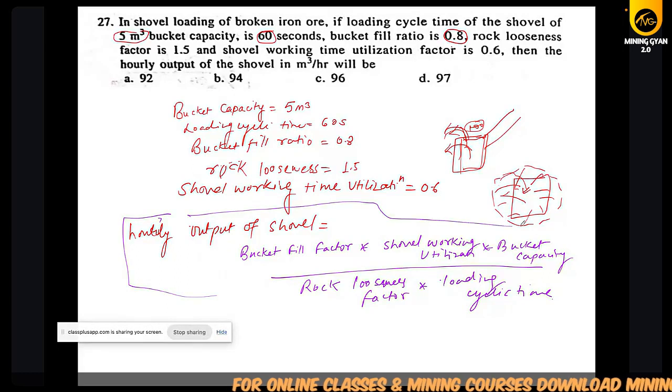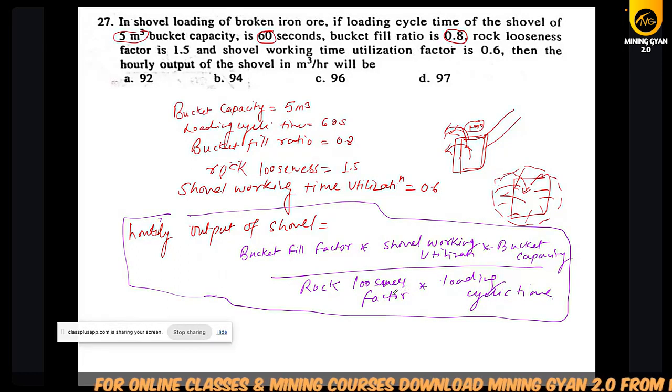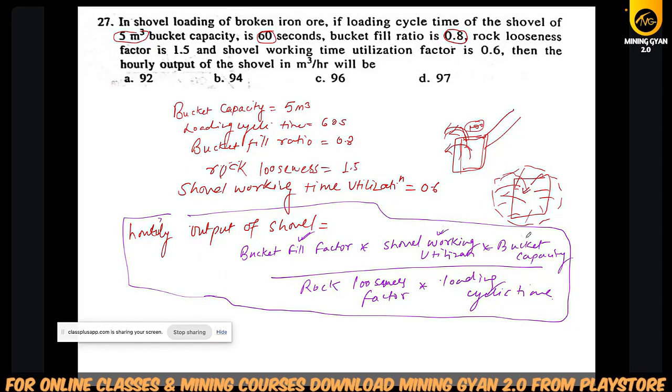Whenever he asks the hourly output of the shovel, you should know the bucket fill factor, shovel working utilization, and bucket capacity. Then you divide by the looseness factor and the loading cycle time.